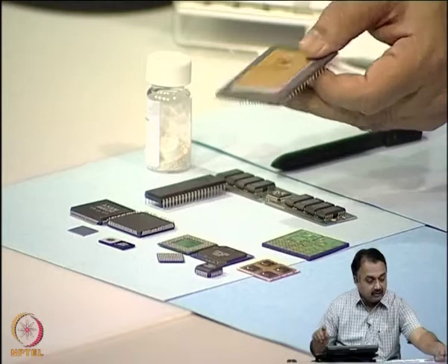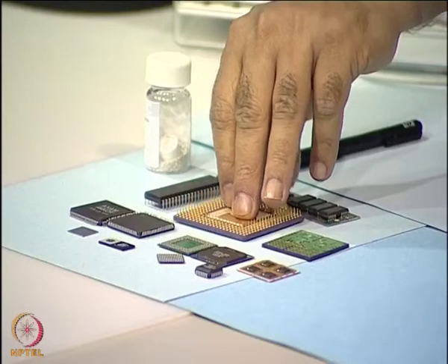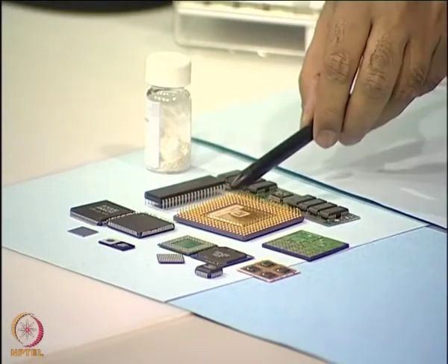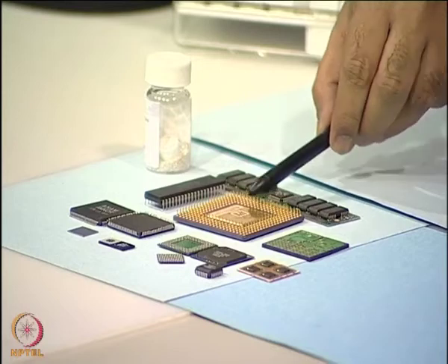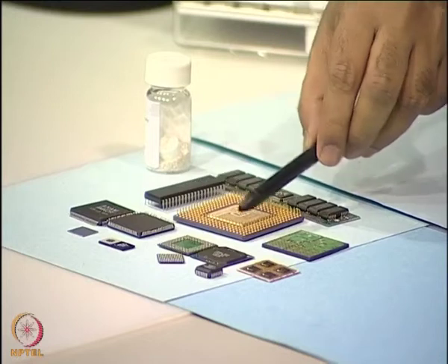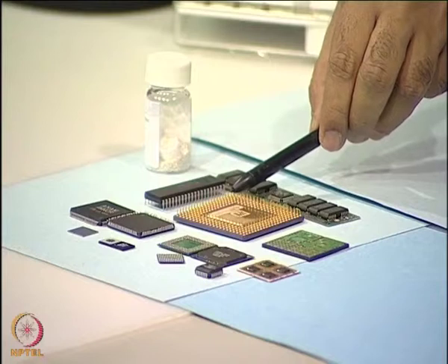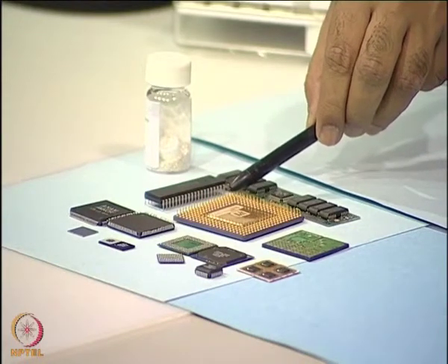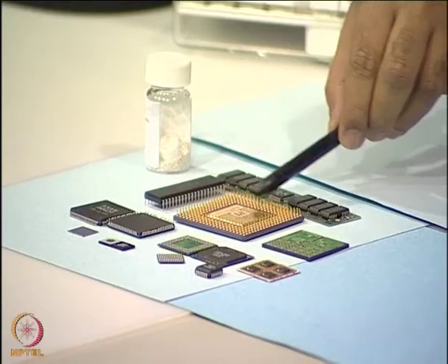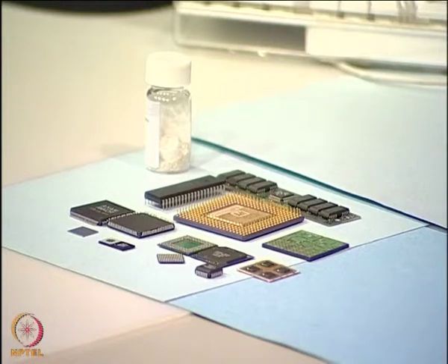This is very large and very heavy. It contains a metal heat sink on top, and then there is a ceramic package, and on the other side you will see a matrix of gold plated pins, which are fairly long, that can go into a PGA socket, typically of a motherboard for a desktop computer that was used earlier. Today we do not really get PGAs for microprocessors in desktop computing, and these are replaced by a very new technology which we will see shortly.